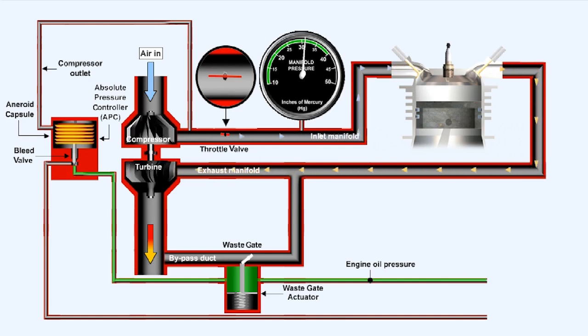Eventually, the wastegate will be fully closed, and the aircraft has reached critical altitude. Above this height, both manifold pressure and engine power output will drop off, despite the turbocharger operating at full speed.